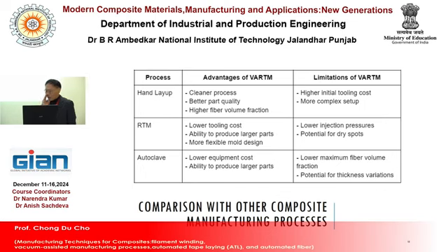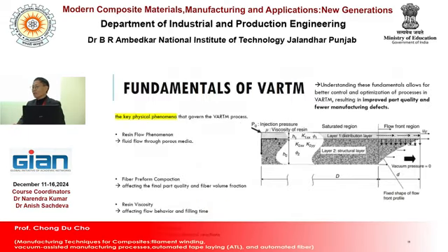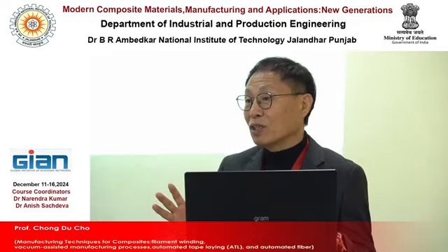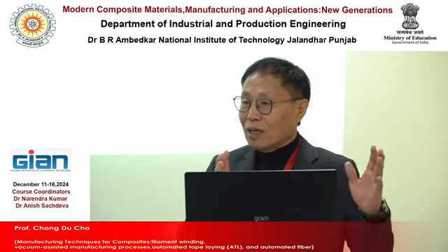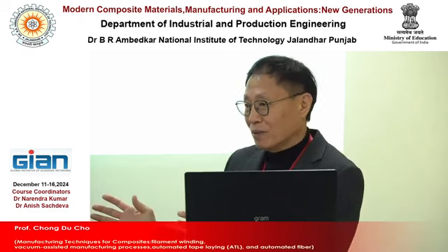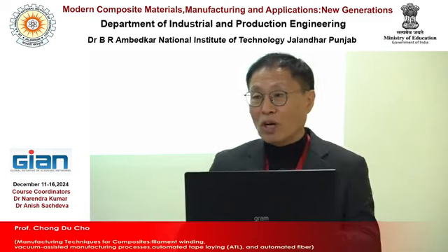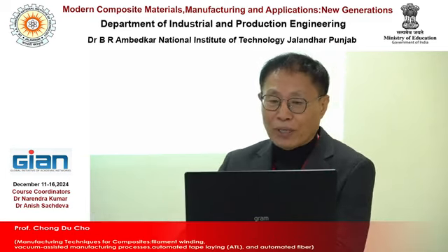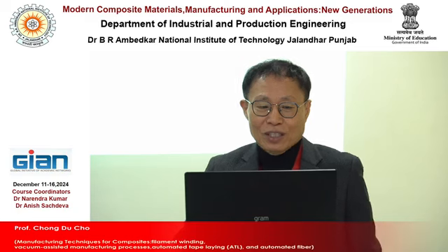So VARTM can be said to be one of the most needed techniques these days. For large-scale composite materials, manufacturing companies use either filament winding or VARTM. That is the case for large structures or composite panel manufacturers.